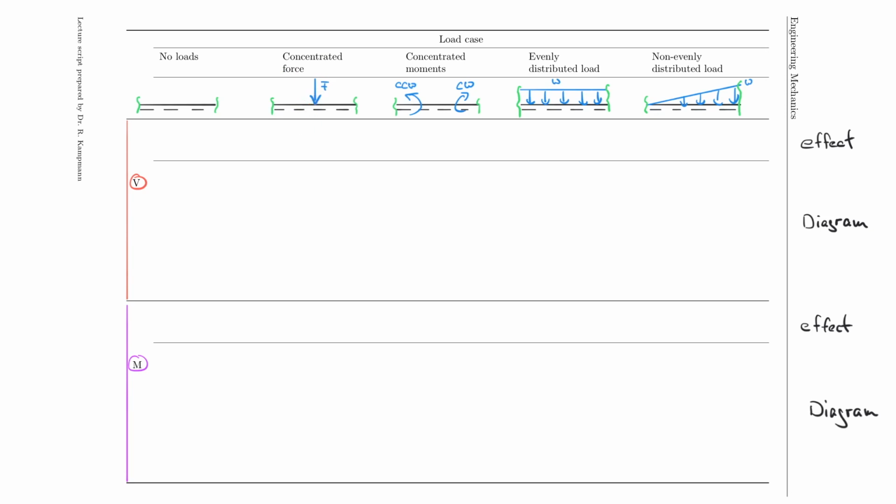Let's remember that the shear force diagram actually encounters a jump or a drop in the diagram. What do I mean by that? I mean that you, of course, have a rigid body, and that one has a jump right under the force at the same amount that the force actually produces.